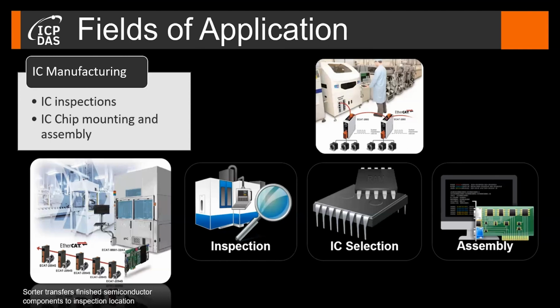The construction of the test facility is quite complex and requires 20 stepper motors to control the entire inspection and sorting process. The customer realized the project by using our real-time EtherCAT PCI master card in a compact industrial PC. The customer uses 5 sets of our 4-axis stepper controller to control 20 axes and precisely control each step in the inspection process.